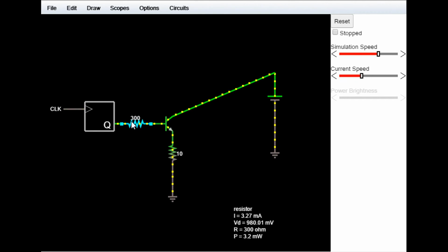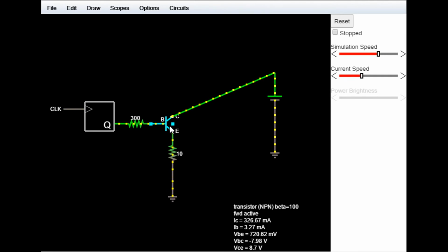And it turns out that all we've done is we've created kind of a weird resistor network where you've got the 12 volts up here fighting with the 5 volts here over where the voltage drop should be over either the transistor or the resistor. And this has come to sort of an equilibrium of sorts. And if you look here, you can see the weird voltage drops over each terminal of the transistor, right?